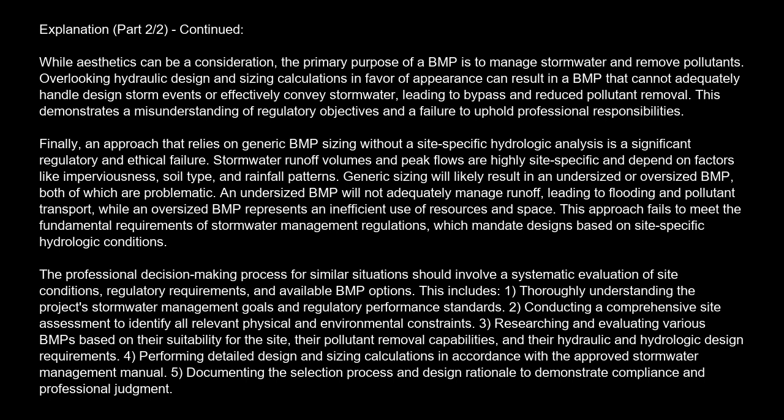The professional decision-making process for similar situations should involve a systematic evaluation of site conditions, regulatory requirements, and available BMP options. This includes: 1. Thoroughly understanding the project's stormwater management goals and regulatory performance standards. 2. Conducting a comprehensive site assessment to identify all relevant physical and environmental constraints. 3.